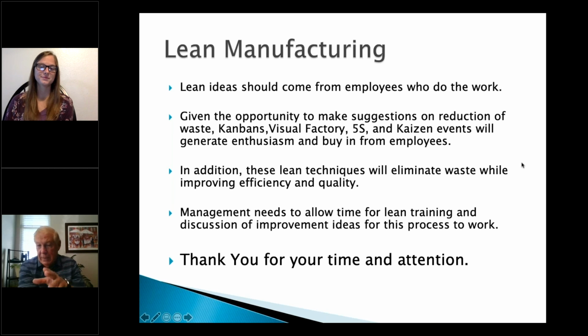So the Kanban feeds the operator, but it doesn't inhibit movement. The parts and materials are available, but they're not on top of them. So that's another safety feature that helps tremendously. So I would say anything on 5S, whether it's sorting, straightening, standardizing, or sustaining, is so safety driven. It makes a big difference.